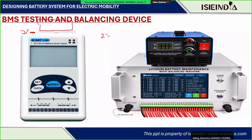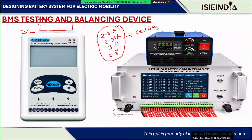Some cell voltage is 2.8 volt, some is 2.9 volt, some have 3 volt, some 2.8 volt. So what we need to do is equalize these cell voltages, and that is called cell balancing. So before testing the complete battery pack, there is one remaining thing: we need to equalize the pack voltage.